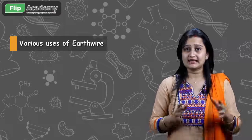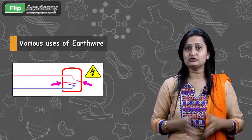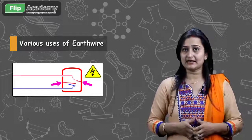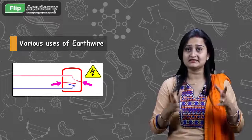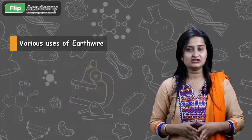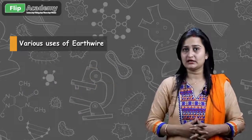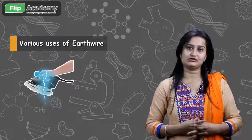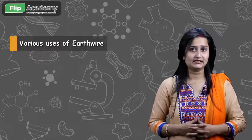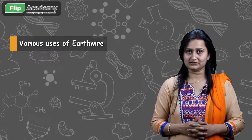So the electric iron which we are handling is in direct contact with the live wire, and the live wire makes that electric iron also live. Now if you touch that electric iron, you will get a heavy electric shock. So in order to prevent these accidents and mishaps, the earth wire is provided.